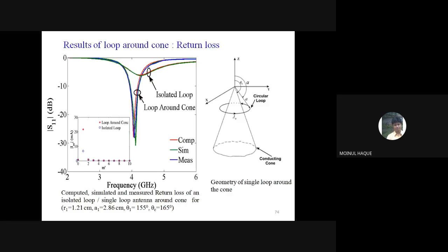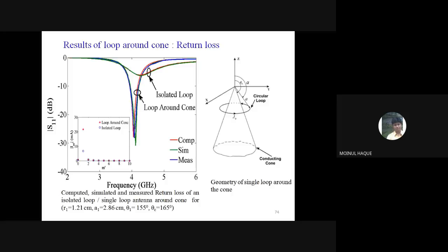Then how will we calculate the width? There is no such formulation, but one thing you should remember is that if you increase the radiating slot width too much, your cross polarization in the radiation pattern will increase, so try to keep it as small as possible. The slot width will contribute to some unwanted modes being generated, resulting in cross polarization, because the current component in that direction will increase. We don't want those current components in those directions, as they will affect our radiation pattern. Thank you very much, sir.